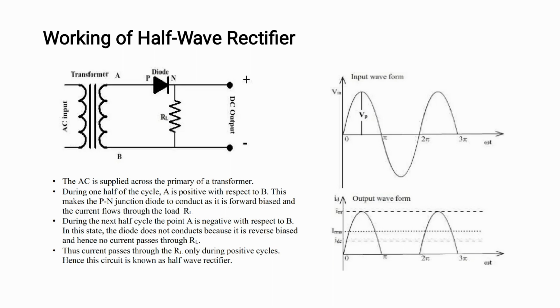After each and every half cycle of the input wave, the AC voltage across the secondary winding reverses its polarity, and the diode is forward biased and conducts current during the positive half cycle of the input AC voltage. That means when the top end of the secondary winding, which is A, is positive compared to its lower end, and at this condition we are considering the diode forward resistance to be 0, but in practical cases there is a small resistance present.